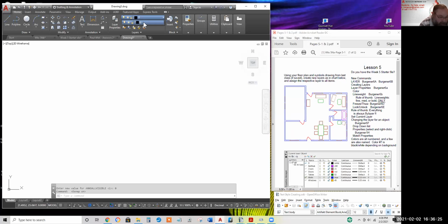In shipbuilding, I'm sure you got electrical, plumbing, hydraulics, ventilation, trim and drain. A different layer for every system, so you can make an entire category red and bold just by assigning those properties to the layer that the lines, arcs, and circles are on. You can't get rid of layer 0. You can't rename layer 0.